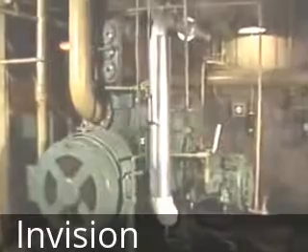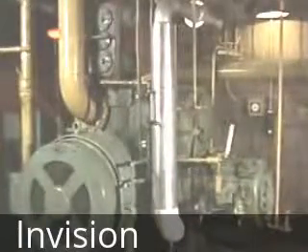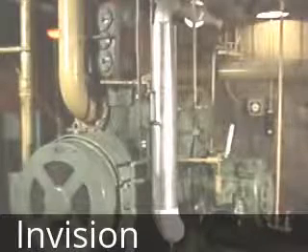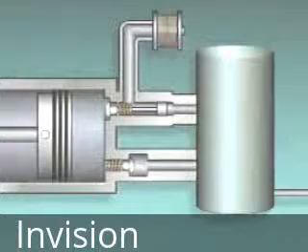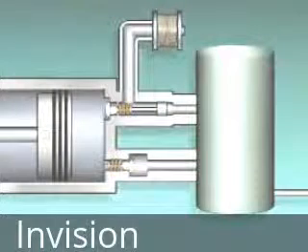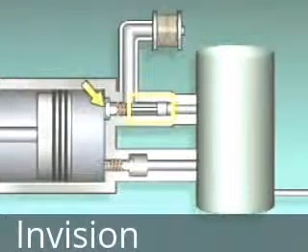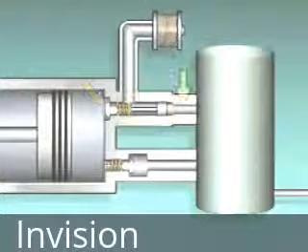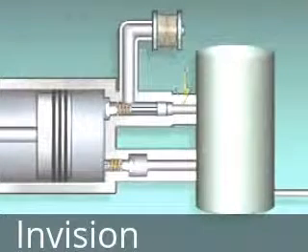Large compressors tend to be more efficient if they operate continually. So one device that is commonly used to prevent overpressurizing the receiver is an inlet valve unloader. This is a simplified illustration of a portion of a compressor system that uses an inlet valve unloader. The unloader consists of a piston and a connecting rod, which is connected to the inlet valve on the compressor. A pressure sensing line is connected from the unloader to the receiver. Gas from the receiver fills the pressure sensing line.